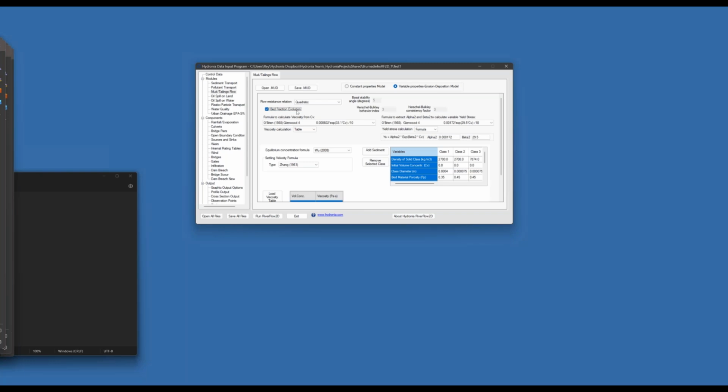So based on the interaction with the flowing material, the granulometry can get coarser or finer depending on the active layer interaction. So that's what we have.